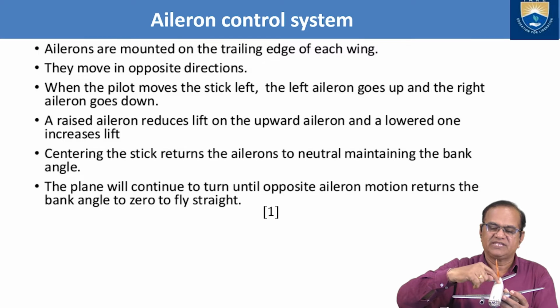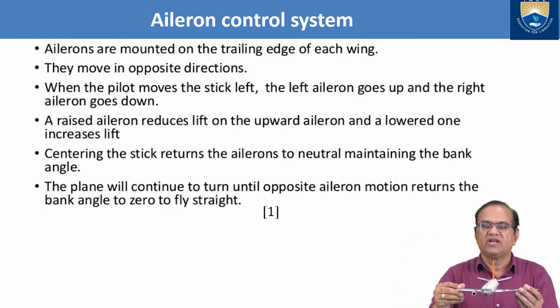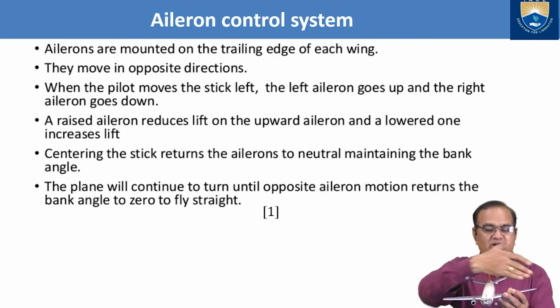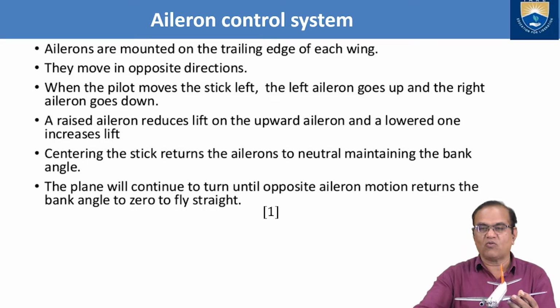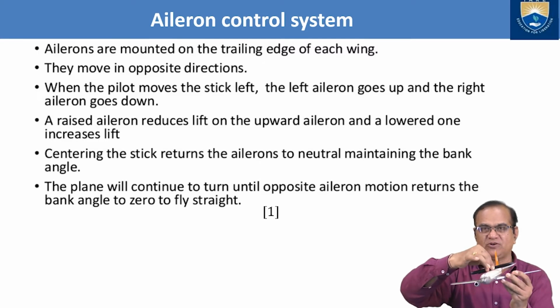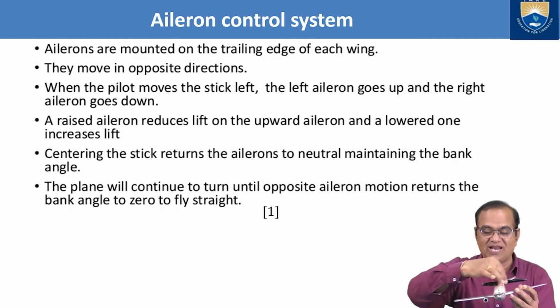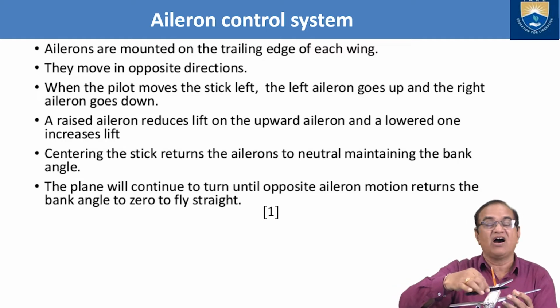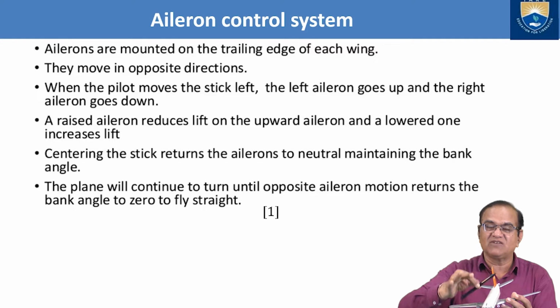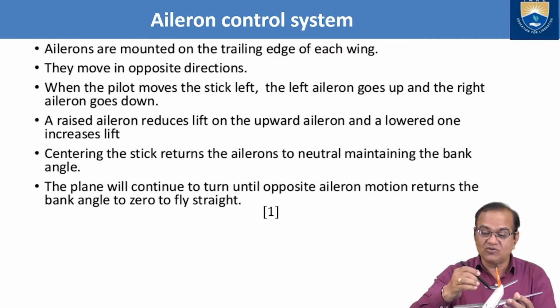So this is the x-axis, y-axis and z-axis. If the motion happens with respect to the y-axis, that means nose up and nose down. Pitching happens with nose up and nose down, with respect to the lateral axis or the y-axis.